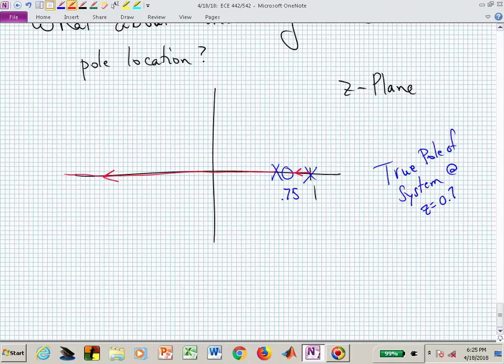And we've picked a gain value, and what's going to happen? Well, for that gain, we'll probably be about where we picked it before, there, but this one will be close to that zero. And that zero is sort of canceling that closed loop pole that's approaching it for that choice of gain k. So what's the net effect? Well, you have this closed loop pole very close to the zero, which kind of goes away. It doesn't completely. And you have a pole about where you set the previous pole for this particular choice of true system pole.